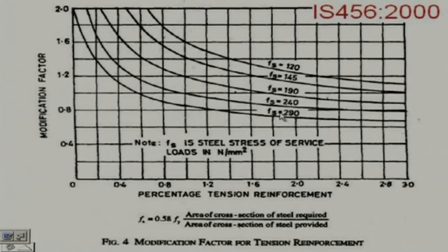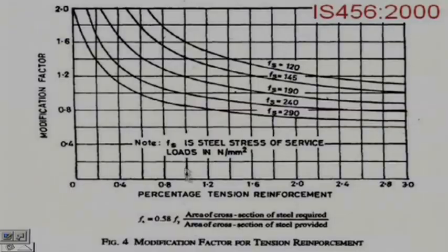Now, how do I know that initially, if we start with, say, a simply supported beam, 20? Here we have to modify the value, but how do I know? That will come from our experiments, what percent of steel we generally use for slabs. On the basis of that we can find out a certain factor, or in another way we have to redesign it. We have to start with the basic value, then do the whole process again, but we generally do not do that, because if we are experienced, then on the very first trial itself we can go.